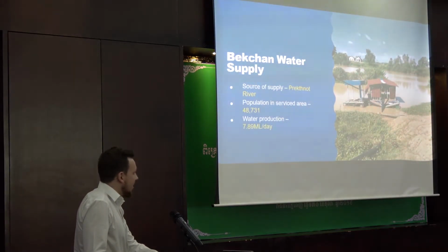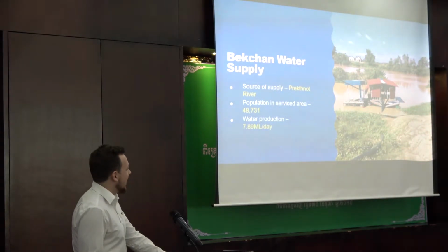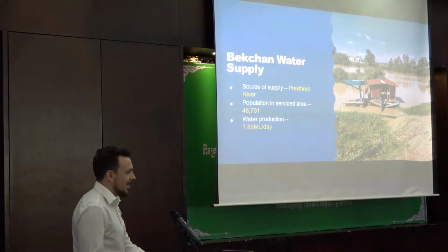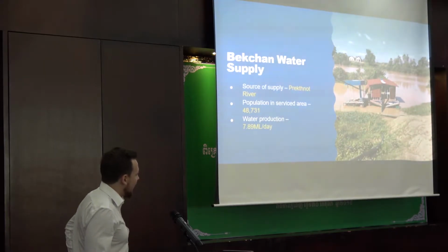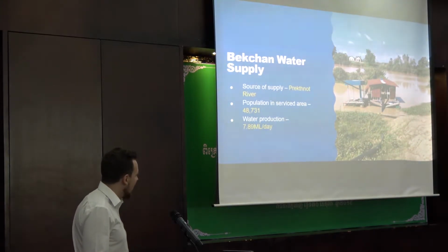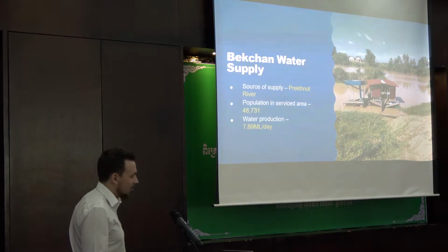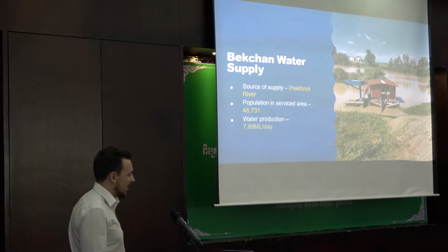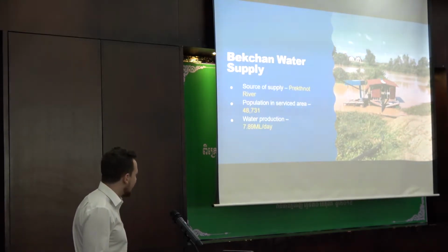So Cambodian Water Supply made it known to us that their biggest challenge is turbidity at the offtake pump. They have a number of sand mine industries upstream that continually backwash sand back into the river, which goes straight down to their offshore pump. They're pulling water off the river, and they're getting turbidity levels in the dry season up to around 600, 700 NTU units.